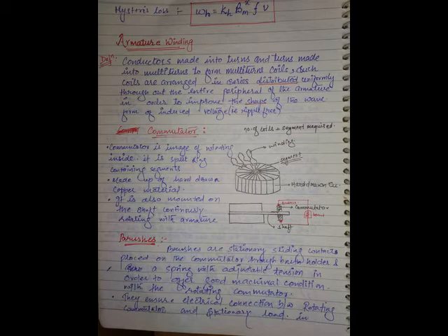But instead of this, there are many slots. I am showing only those slots because you are placing them in those two slots only. If you concentrate all the conductors in making two coils, how many slots do you require? Only two slots, right? So let us say one thing like this. You placed one here and one here, all bunched together, placed like this. So this is north and this is south. This is one thing. Instead of doing this,